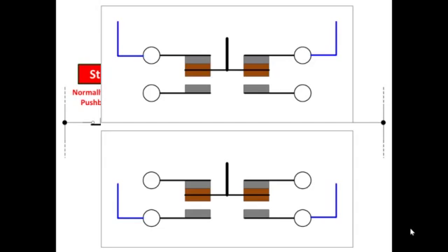Separately, you buy a contact block. The contact block that you're looking at here, you're looking at two of them. It is the most common contact block. It has one normally open, one normally closed. The top contact is normally closed, the bottom one is normally open.